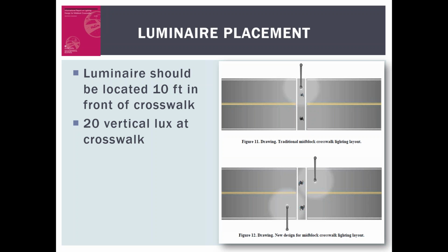I wonder if you have any comments on how to maybe place lighting at interchange locations and some things to consider when doing so. Yeah, that is a big concern, and you have long underpasses where the pedestrian is going alongside a roadway where you probably have to provide day and nighttime lighting. Tunnels too may have to provide daytime and nighttime lighting depending on the length of the tunnel, not only for the visibility and safety of the pedestrian, but also for security concerns. But making sure that there's a uniformity of lighting, and that the lights are lighting the sidewalk area before the pedestrian enters the roadway.